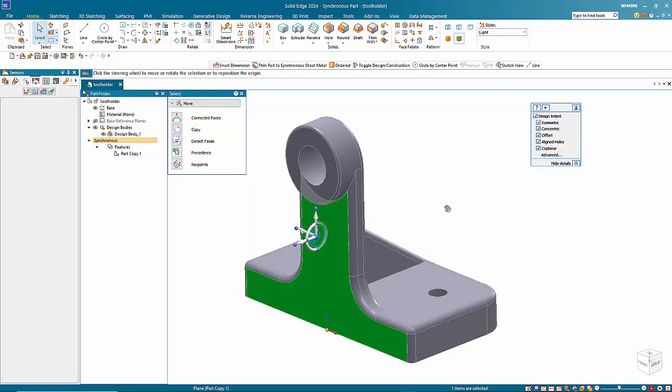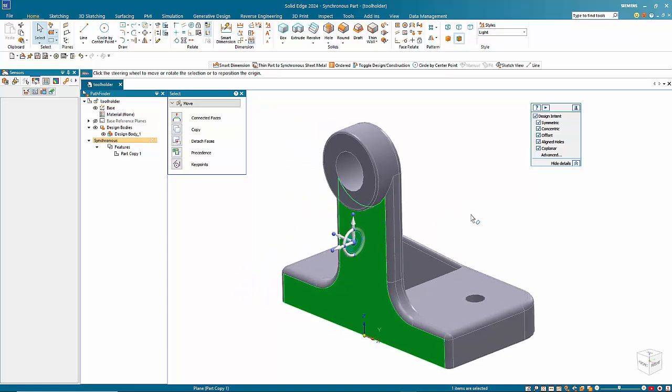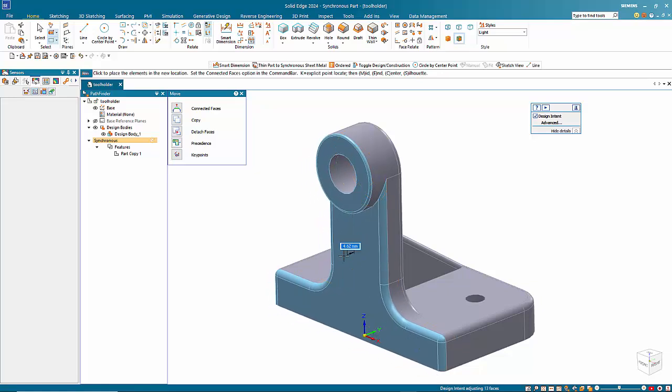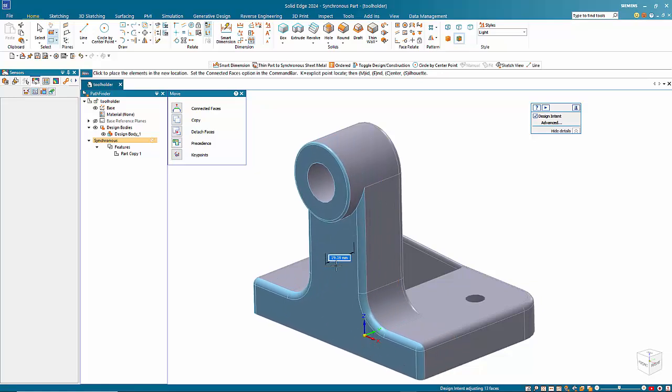You'll notice it sort of dropped a lot of the geometry at some points if you go too far. Obviously, it can't recompute. Now, if we wanted to, we could hold the control key down and add in an extra face. If we want to maintain our offset between the two on here, we can then just drag that out and make the whole thing fatter.